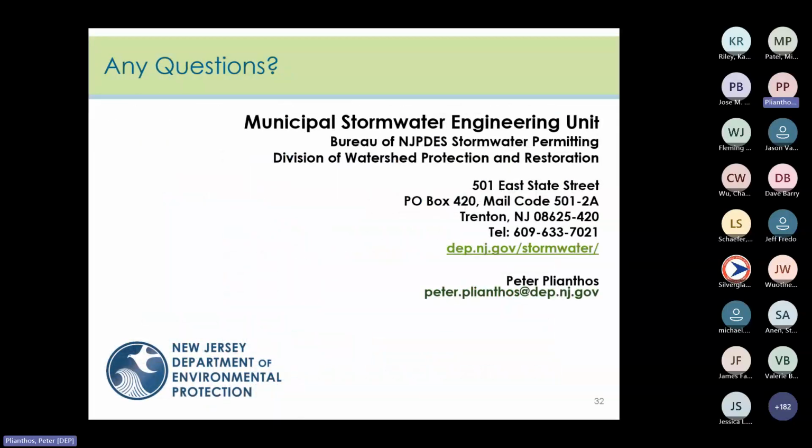So if you haven't read it, Chapter 13 includes a lot more examples. Please see Example 7 in the chapter for guidance when replacing soil below an infiltration BMP. Also see Example 8 for the situation where exfiltration is used in the routing calculations, and a mounding analysis is done for the volume exfiltrated for the 100-year storm. Additionally, Chapter 5 includes examples with groundwater mounding analyses and includes exfiltration in the routings, which is allowed in certain circumstances for the green infrastructure BMPs.